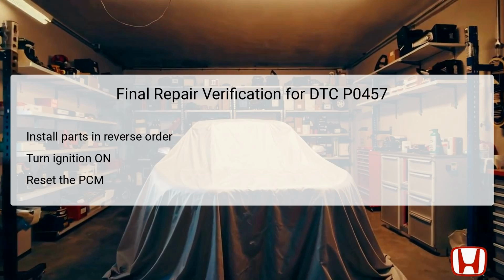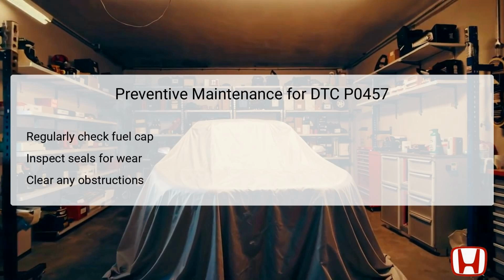Finally, conduct an idle learn procedure to optimize the performance of the vehicle. This step is crucial to recalibrating the system and ensuring everything functions as intended. Once completed, you can recheck the system using the EVAP test to confirm that no DTCs remain. Preventive maintenance is key in ensuring that the DTC P0457 does not resurface.